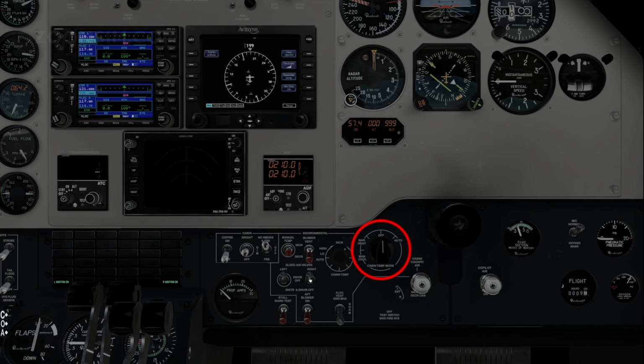Cabin temperature mode, auto. In the auto position, the air delivery system establishes the requested temperature. The requested temperature is set through the cabin temperature level control switch. Cabin temperature as required.